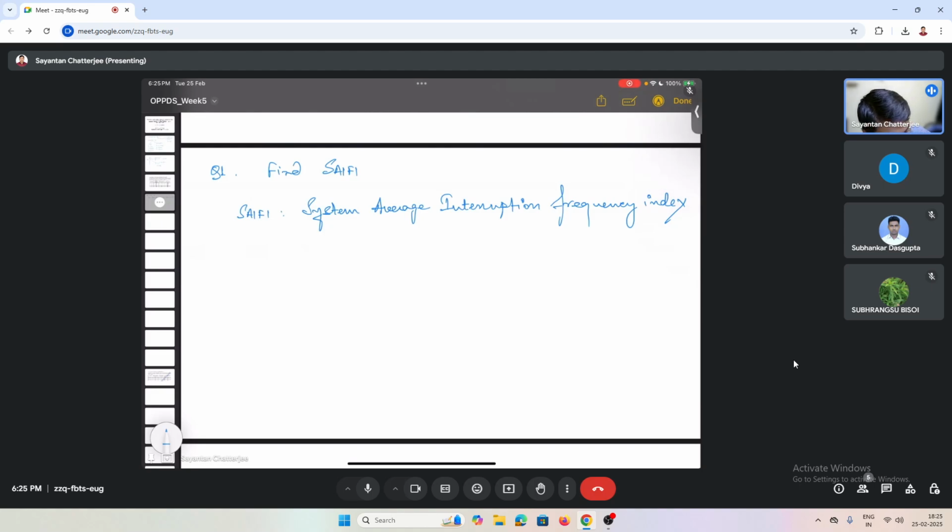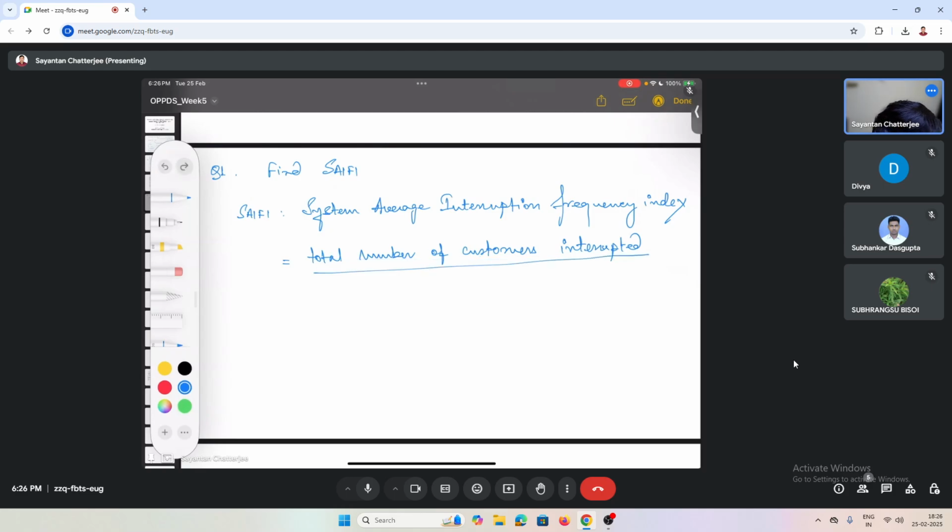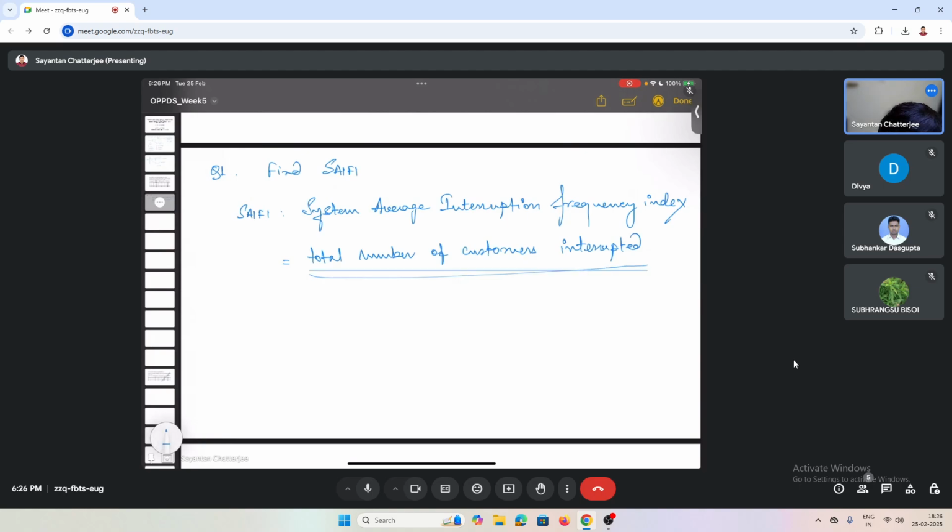Okay. And what is the formula of SAIFI? As we all know, it's the total number of customers interrupted divided by the total number of customers served.